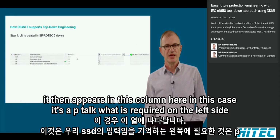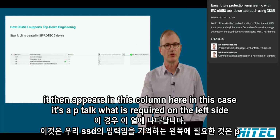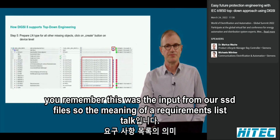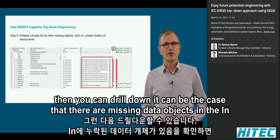It then appears in this column here. In this case, it's a PTOC, what is required on the left side. You remember this was the input from our SSD file, so the meaning of a requirements list. Then you can drill down. It can be the case that there are missing data objects in the LN.